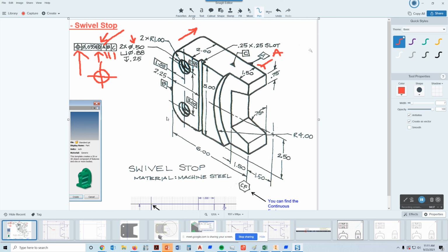I think I've mentioned that when holes are drilled crooked, and then you've got another hole and it's also crooked, and we call that crookedness attitude, if you try to put a bolt through both of those holes, that's where you're going to have the maximum amount of trouble assembling two parts, if the holes are not within a tolerance that controls their perpendicularity. Okay, so essentially we're trying to make sure that the center axis of the bolt can go through both holes, even though the hole's center axis may have some attitude to it. Okay, does that make sense to you guys?